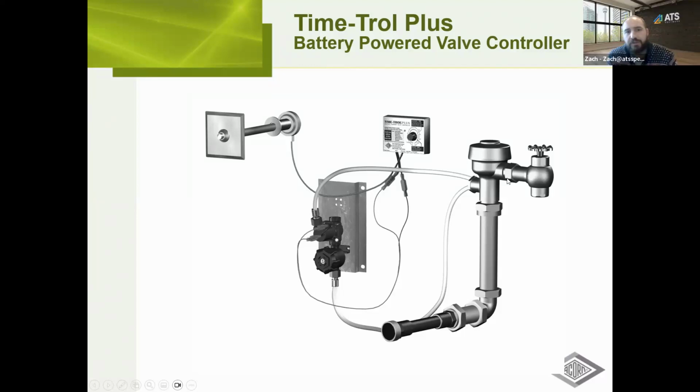And I see you've got the hemispherical push button shown for the flush valve activation. I know there are 2 options for the push button style: the mechanical push button and a piezo, which senses the electronic signal in your body to activate, right? Does the piezo work with both Master-Trol and Time-Trol, or just one? No, it works on both. Perfect, because I know that's a great ADA, OBC or BC building code barrier-free option. Yeah, the piezo button can be used on both types.